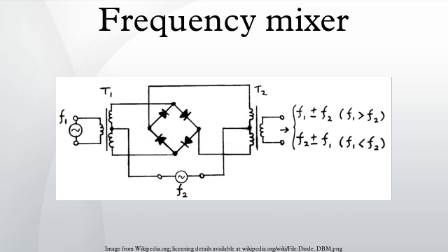Diode: a diode can be used to create a simple unbalanced mixer. This type of mixer produces the original frequencies as well as their sum and their difference. The significant property of the diode here is its nonlinearity, which means its response is not proportional to its input. The diode therefore does not reproduce the frequencies of its driving voltage in the current through it, which allows the desired frequency manipulation. The current I through an ideal diode as a function of the voltage V across it is given by, where what is important is that V appears in e's exponent.